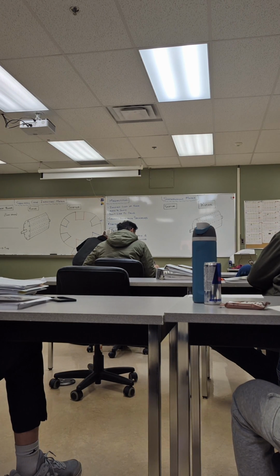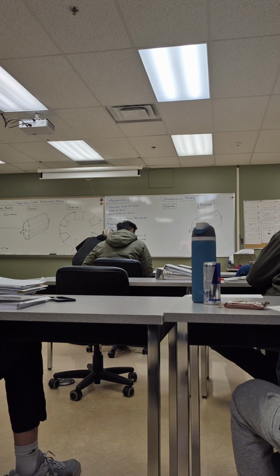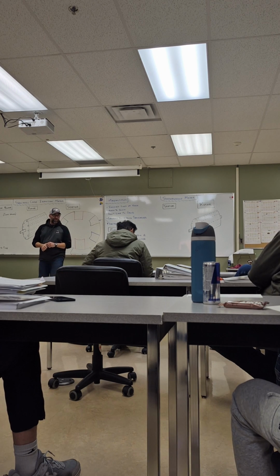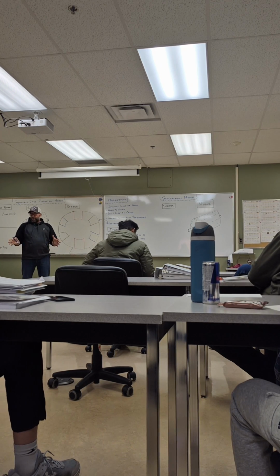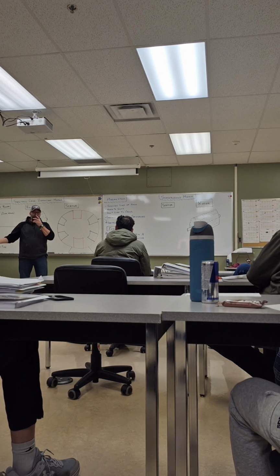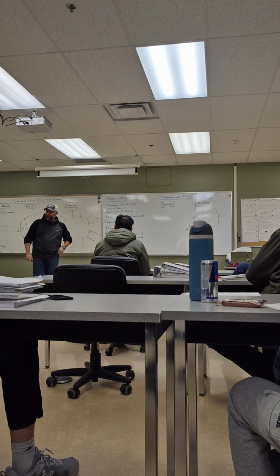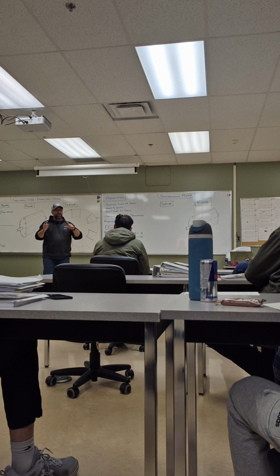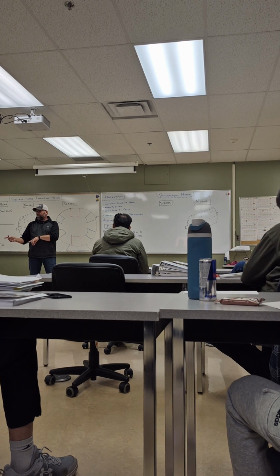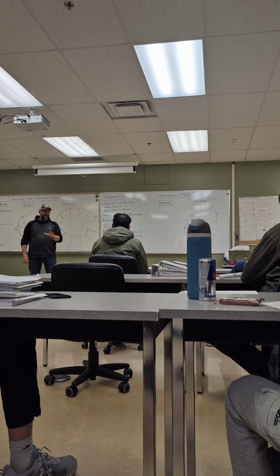Did you say on, not in? Yeah, it doesn't matter. I use in for current. Current flow is in a conductor, voltage is induced on a conductor. Voltage we call potential, nothing's happening. It's potential energy. And so you'll see it probably in this book. We induce voltage, we don't induce current. You hook that voltage to something, current then happens. So you don't induce current directly, you induce volts. And that is induction in a nutshell.